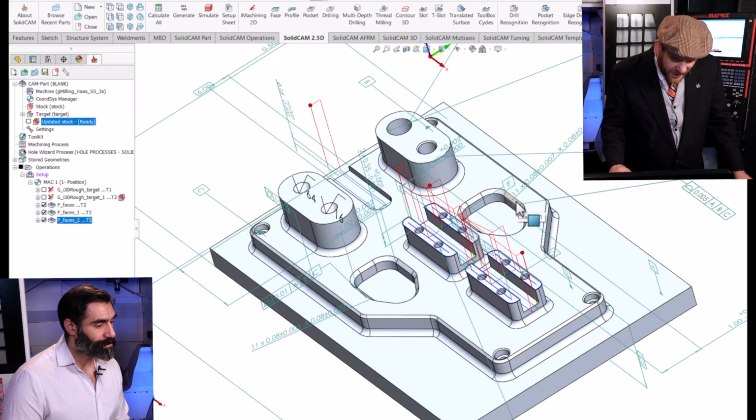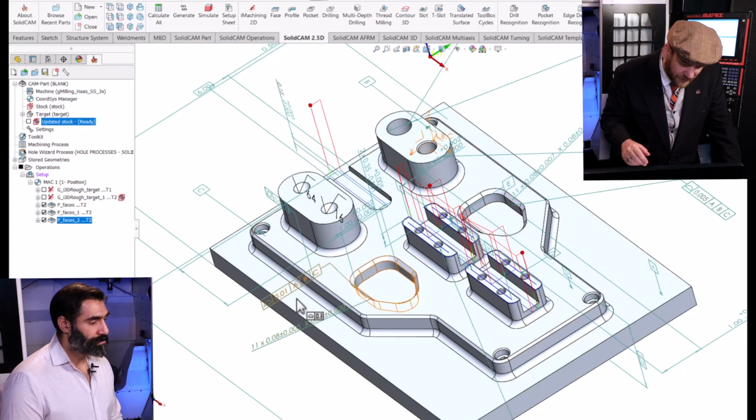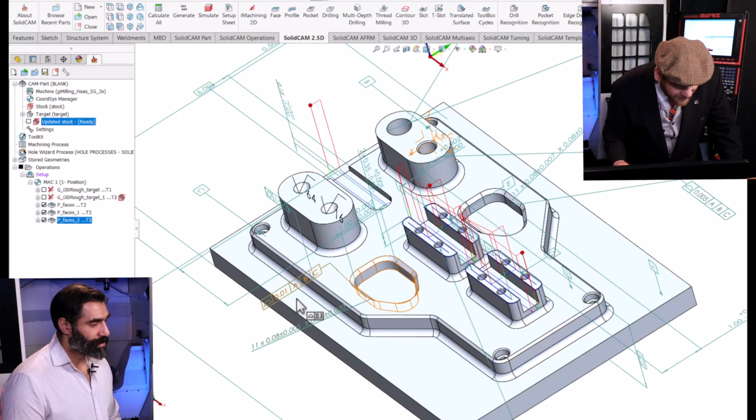exactly alike. And if you were to just give me a solid model with no MBD on it, and the blueprint has coffee spilled on it, or it's lost, or I have the wrong rev, I might not know these pockets are very different. This pocket here has a profile tolerance of 10 thousandths that I can see, which is relatively open in modern manufacturing.